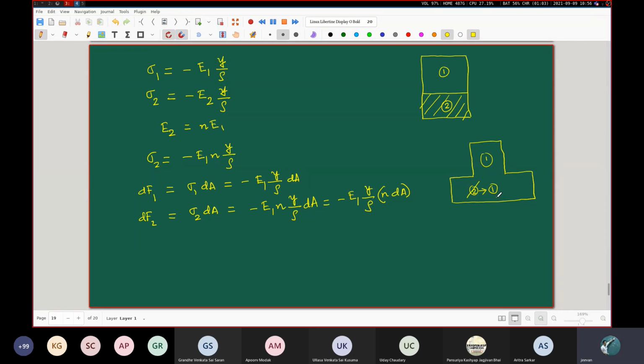Okay, so this becomes our transformed cross section. This is referred to as the transformed cross section. The good thing about this alternative way of looking at it is that we are all familiar by now with finding the centroid, the second moment of area, and the stresses for this kind of cross section. For this very simple example, the rectangle transforms into a T-beam, a T type of cross section, which we have just done.